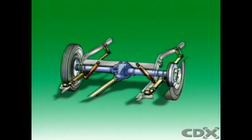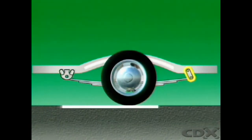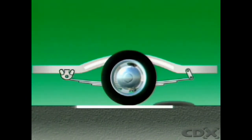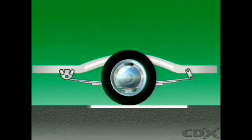On vehicles with non-independent suspension, leaf springs provide a simple means of performing these functions. On a rear-wheel drive vehicle, the axle housing is located on the spring by the spring center bolt and clamped to the spring by U-bolts. Since the front eye of the main leaf is located on the frame at the fixed shackle point, the spring then prevents the axle moving longitudinally. A swinging shackle at the rear allows the semi-elliptical spring to flatten out under load, which provides for vertical movement. As well, the driving forces can be transferred through the spring to the frame.